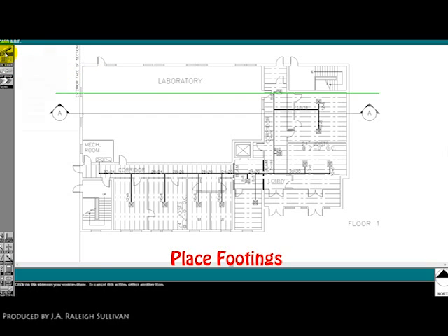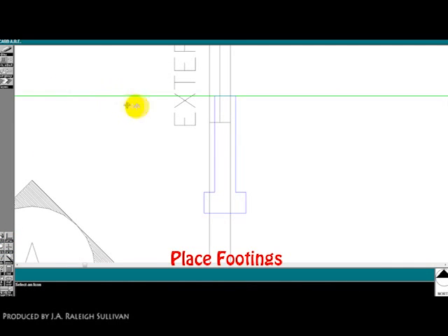Now put the footings in. Just plop them in their general locations, and we will precisely adjust them when we zoom in a moment. We need footings at all exterior walls and any interior bearing walls. Note that the program states a frost depth. In our case, it must be at least 5 feet deep.